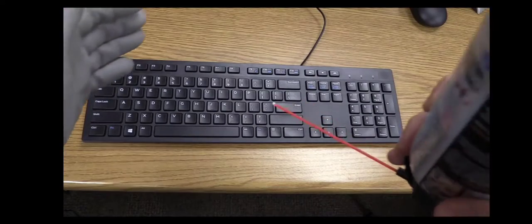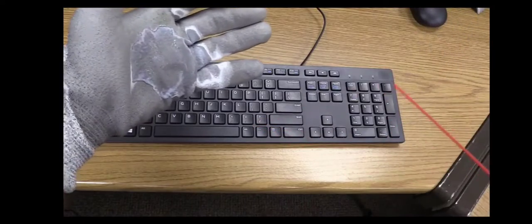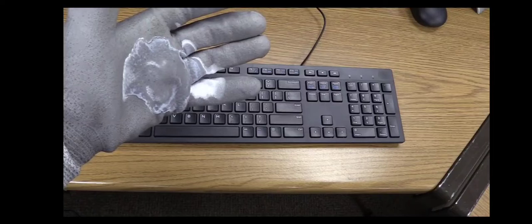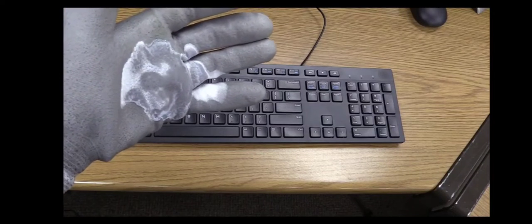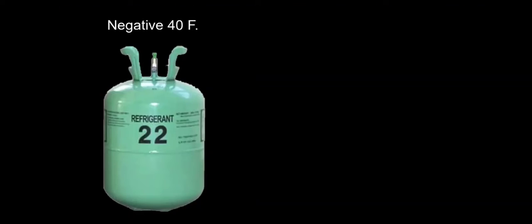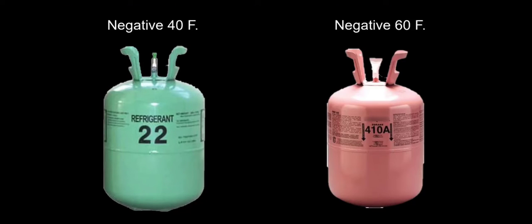And if that liquid refrigerant leaves this can, it evaporates very quickly. And that liquid evaporation is going to extract a lot of heat from whatever it touches. And it can cause some mild skin irritation or frostbite, all depending on the amount of liquid that hits the skin. Now R22 boils around -40 degrees, and R410A around -60. You'll always want to wear gloves when removing refrigerant gauges from these systems.